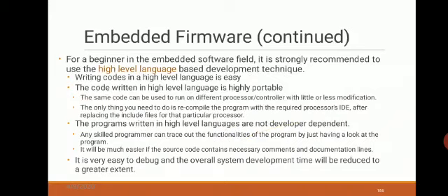Writing code in high level language is easy. The code written in high level language is highly portable. When you write embedded C and you have dumped it on some embedded system and you want to port it, I hope you understood what I mean by port: it is changing the devices. When you want to port, it is highly easy. It is very easy to port code written in high level language. The same code can be used to run on a different processor or controller with a small modification. The only thing you need to do is recompile.